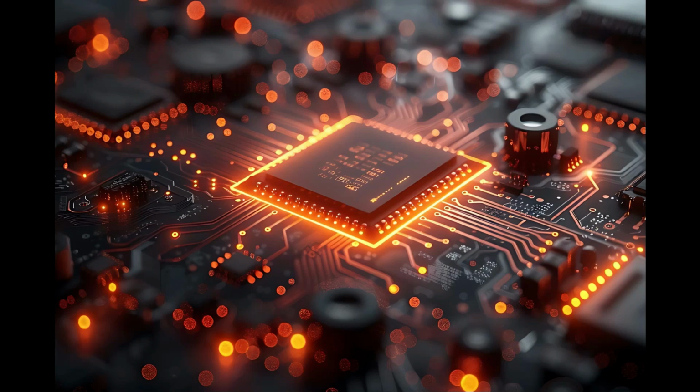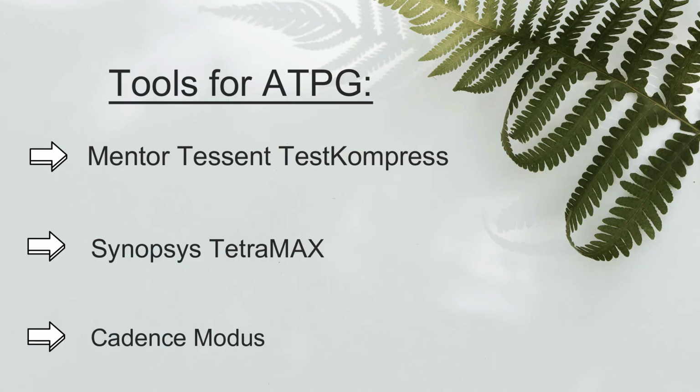So, we require a tool that generates patterns for us to test manufacturing defects in chips. These are commercial ATPG tools we primarily use as DFT engineers to generate test patterns. We have Tessent TestKompress, Synopsys TetraMAX, and Cadence Modus.